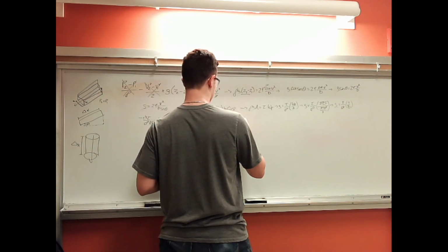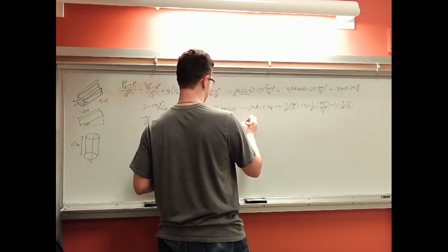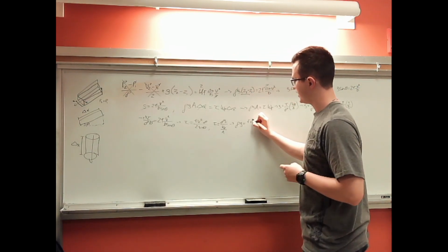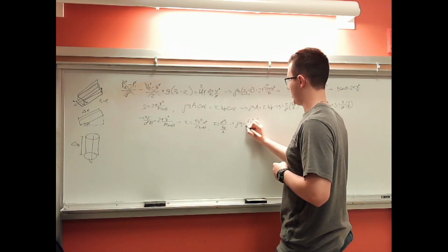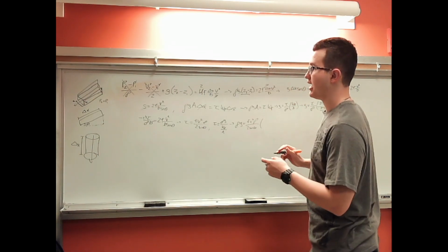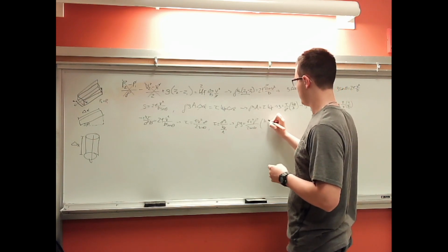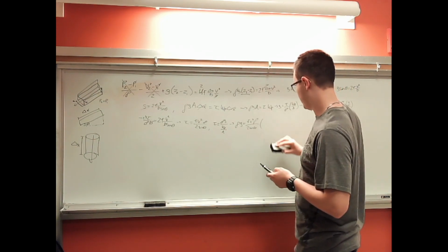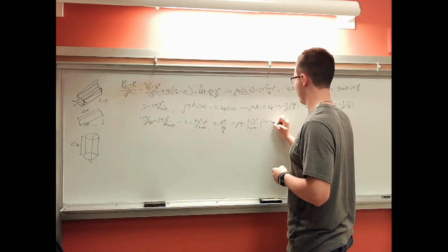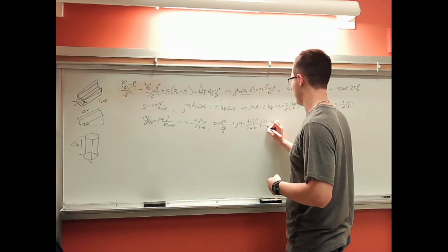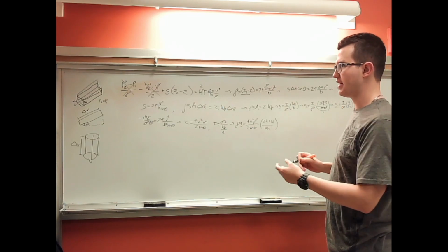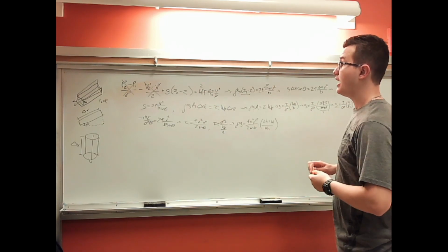It will be density times gravitational constant is equal to Fanning friction factor times velocity squared times the density divided by 2 sine theta multiplied by 2h, 2 times the height of the liquid, plus the width of the channel, the width of the liquid, divided by wh. Width times height, the area of a rectangle.